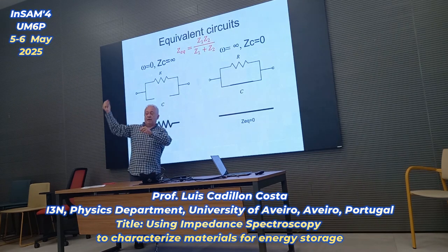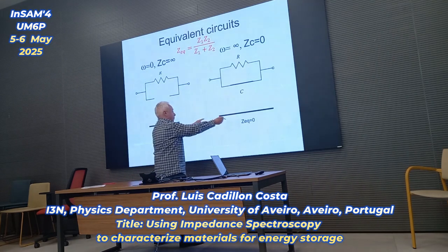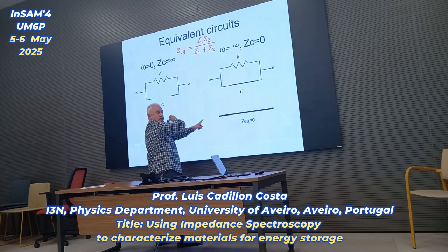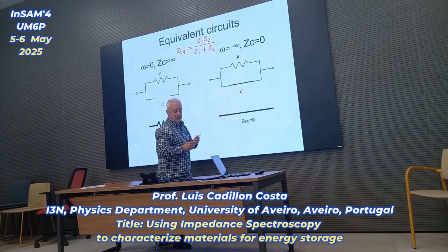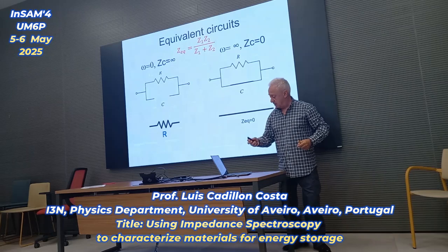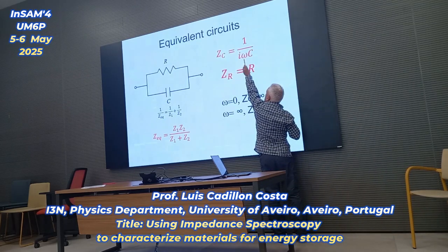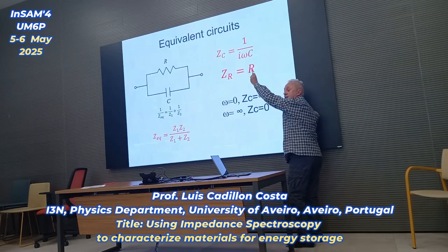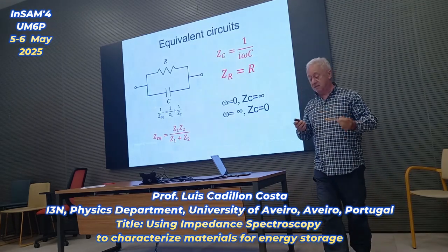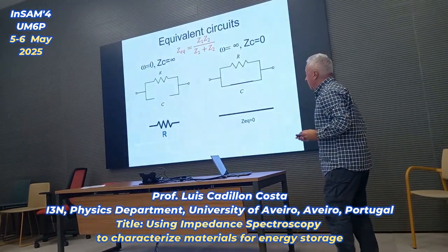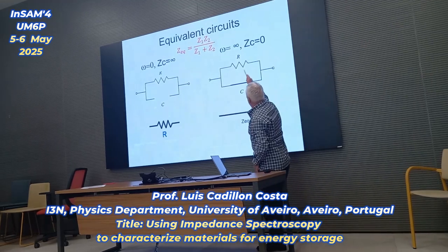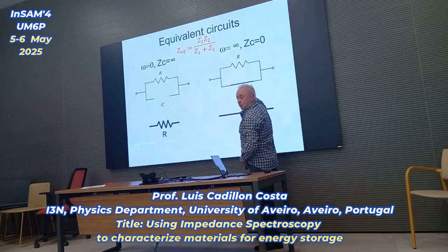When I increase the frequency, that means when I go to this side, for infinite frequency, the impedance of the capacitor is 0. If it's 0, it is a short circuit. So in this case, 0 in parallel with R is 0.